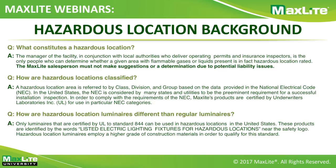Most of us are familiar with UL 1598, which is essentially the UL rating for all LED luminaires. However, for a LED luminaire to be used in a hazardous location rating, it must adhere to standard UL 844. This is actually a pretty difficult standard to achieve. There's only one UL lab in America that actually tests to this standard, and therefore this is not a very common portfolio for most standardized LED manufacturers to have unless they're one of the larger Big Four.